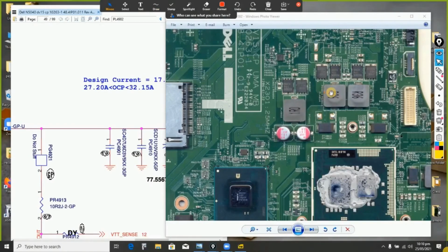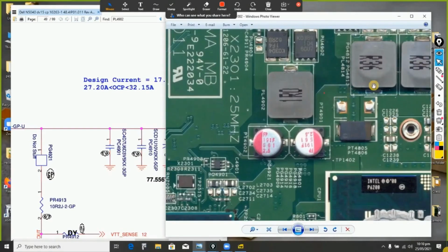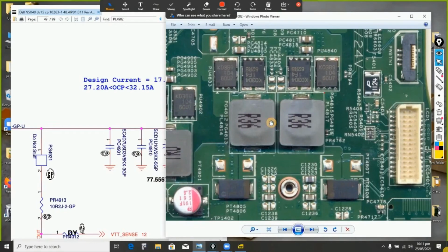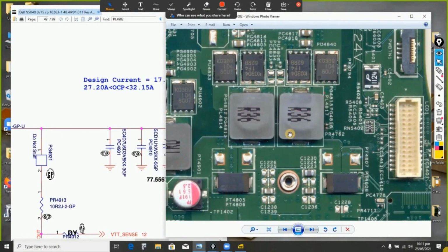The reason why they are using 2 coils for this CPU is only because this CPU needs very huge power, current. So therefore they are using these 2 coils to support each other in order to power the CPU, and it's always the last voltage to be generated on the motherboard. Practically this statement is not too right, but theoretically that is the message.